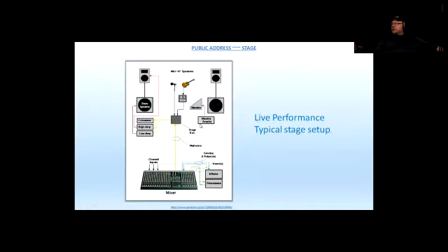The reason for that is that the stage speakers are usually 8 ohms or mostly 4 ohms. So when you have the wiring going from the stage box to the speakers that are on the stage, the distance that the wire has to cover is minimal. If we had the wires going from amplifiers placed at the front of the house, which would sometimes be somewhere close to halfway to the public seats, then the wires would be longer.